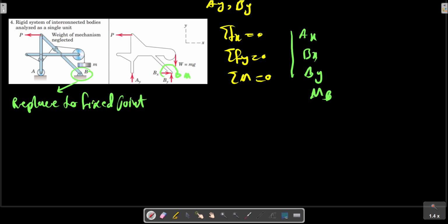Therefore, there would be four unknown supporting reactions acting on the beam, namely the force at A, the two components of force at B, and the couple at B as I write here. Consequently, the three independent scalar equations of equilibrium would not provide enough information to compute all four unknowns.